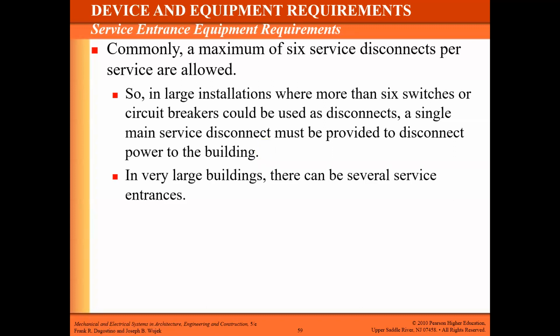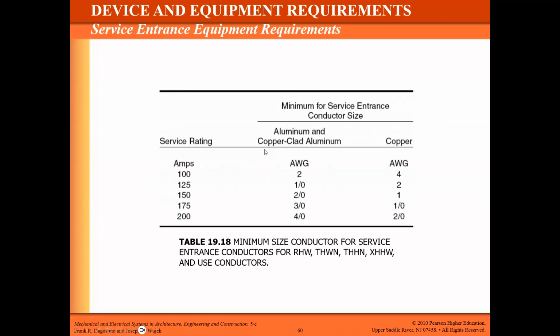The idea there, I think, is that more than 6 is just going to take too long to shut off all the individual ones in the case of an emergency. So one single switch would run those individual switches. So you can either shut off one portion of the building or the whole thing all at once with that single switch. The conductor sizes for the various pieces of equipment, those conductors coming into the building, the ones that are feeding right off of the transformer, need to be sized fairly large. And so you can see the different sizes that we have here.